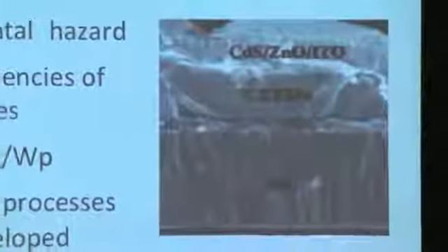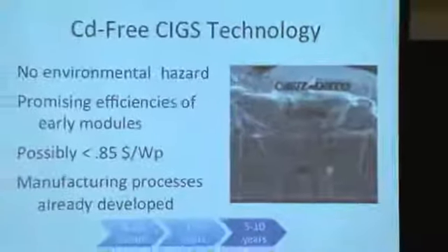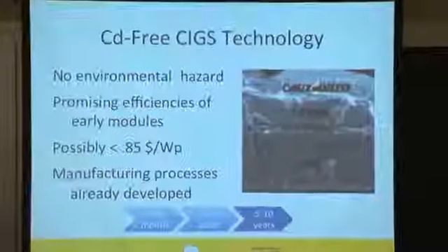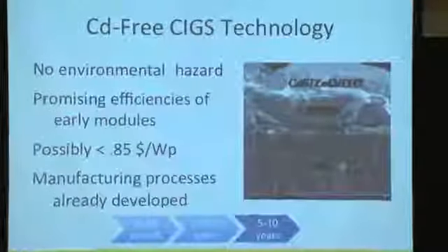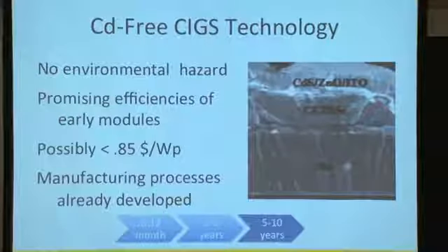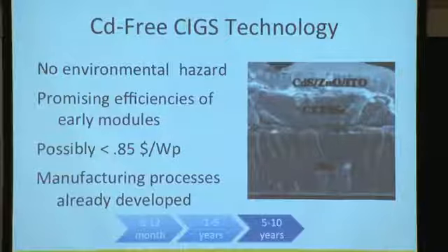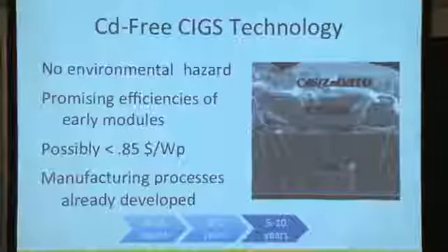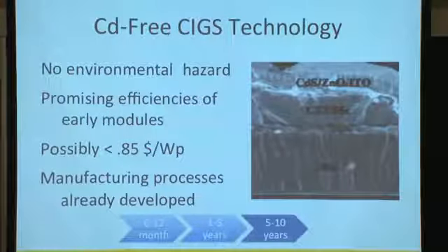Another thing that stood out to us was actually cadmium-free CIGS technology. And as Ben mentioned, cadmium has a huge environmental impact and would require a recycling process, which is not practical given this context. So we looked at a cadmium-free CIGS technology that would actually have the benefits of thin films in their low cost and moderate performance, but not have the actual environmental concerns associated with them. So currently in lab, there have been a few options to replace the cadmium sulfide buffer layer.